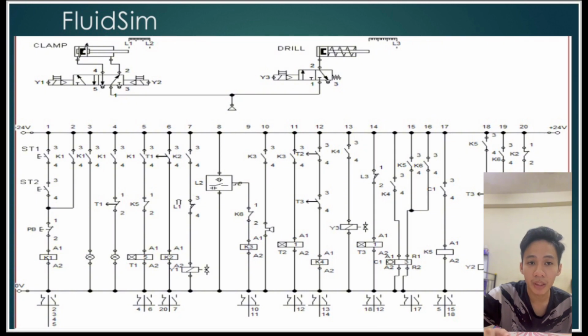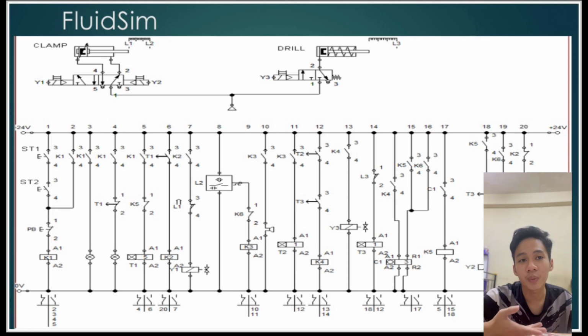After the L3 is open, it will touch the timer again, but this is a different timer, T3, and it will switch off the switch from line 12. As we can see, in line 12, there are two limit switches. When T3 is triggered, the T3 limit switch is broken, and then the relay will retract.